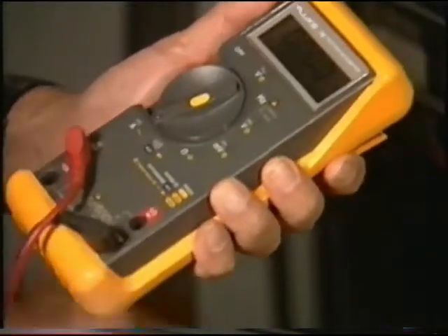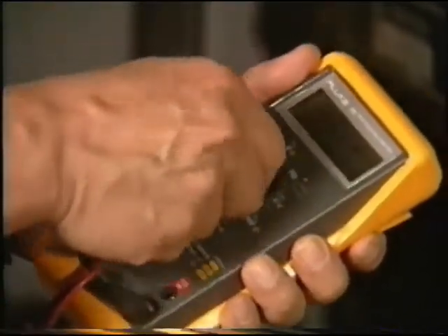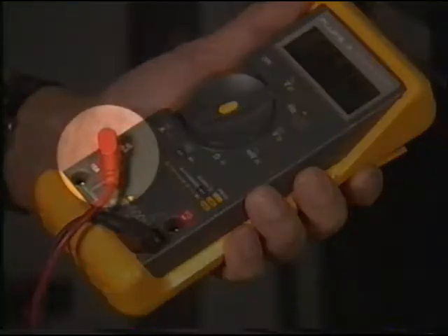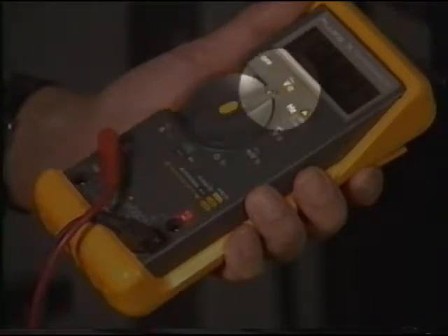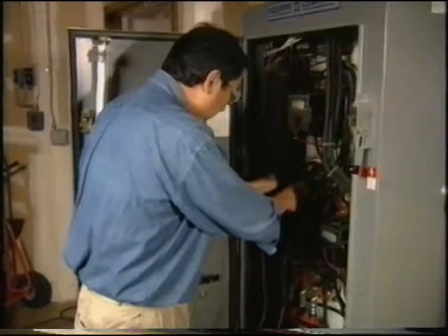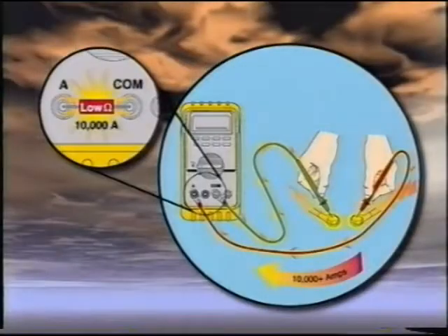In fact, one of the most common misuses of handheld multimeters can cause a similar chain of events. If the user leaves the leads in the amp's input terminals and then accidentally connects the meter leads across a voltage source, he has just created a short. While the voltage terminals have a high impedance, the amp's terminals have a very low impedance. That's why the amp's terminals must be protected by fuses. These fuses are the only thing standing between that user and a potential disaster.